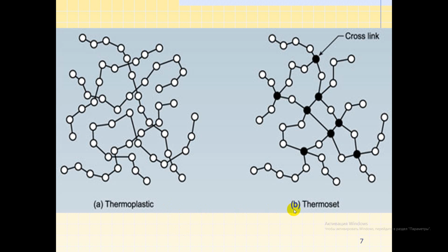Thermoplastic and thermosetting plastic. The primary difference between the two is that thermoset is a material that strengthens when heated, but cannot be remolded or heated after the initial forming, while thermoplastics can be reheated, remolded and cooled as necessary without causing any chemical changes.